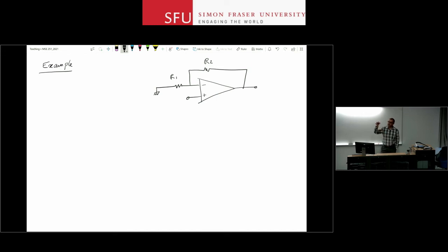So it's like you have a voltmeter or oscilloscope and you want to measure the voltage at a node in your circuit, but you don't want the oscilloscope or probe of the voltmeter to load that node. You don't want the voltage at that node to change when you touch it, right? Because as soon as you touch it, remember, the probe that you're putting here is going to effectively add its input resistance to that node. So if that input resistance of the voltmeter is comparable to the impedance in that node, you're going to change the voltage at that node.